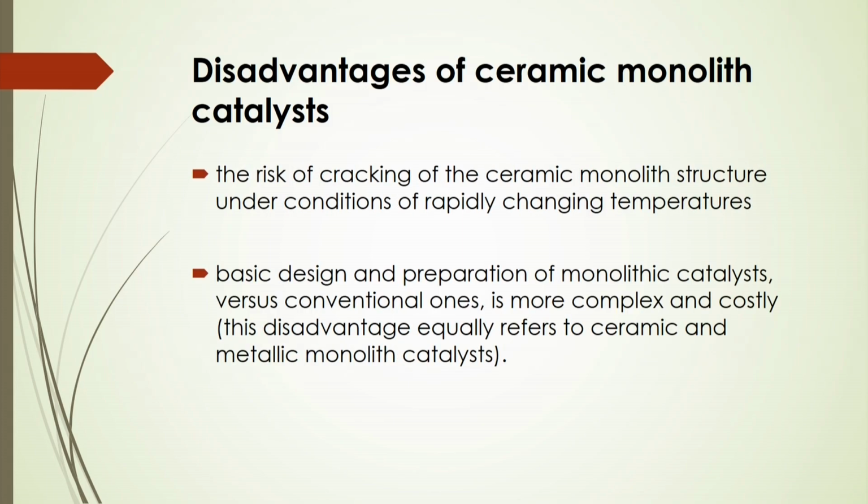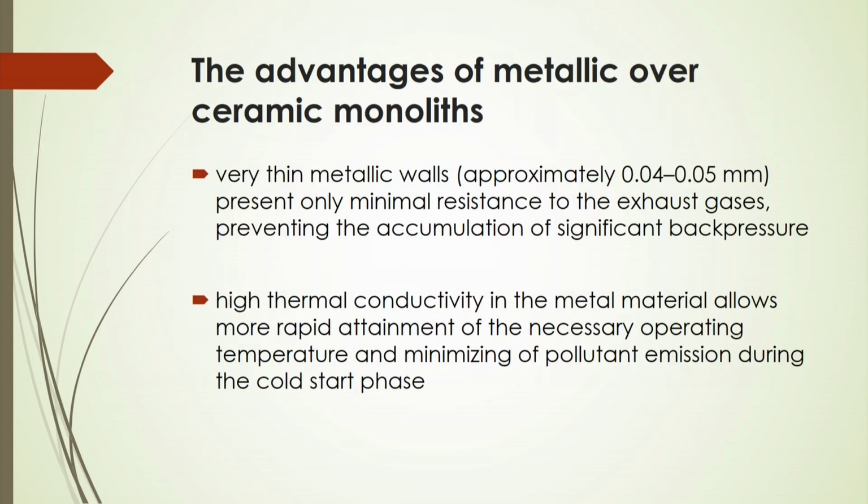Also, there is a risk of cracking of the ceramic monolith structure under conditions of rapidly changing temperatures. The basic design and preparation of the monolithic catalyst versus conventional ones is also more complex, and it should also be cost effective. So, the disadvantages apply equally to ceramic and metallic monolithic catalysts. These are some disadvantages you can say.